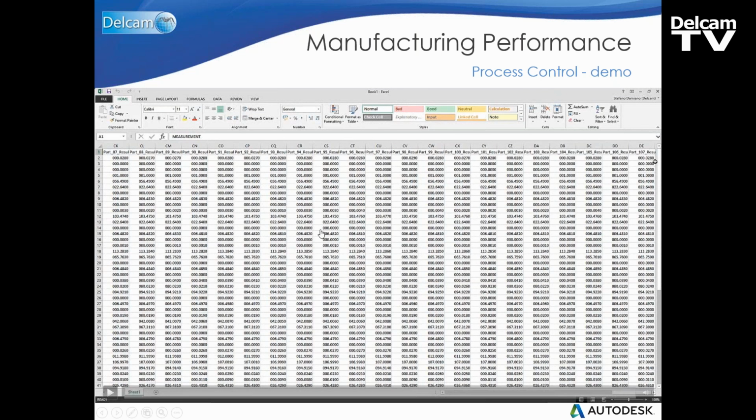We can use the data in the middle here to monitor how the process for a certain feature might fluctuate across the batch of components. And if we identify that it's getting close to our tolerance, or if we need to intervene, then of course we can update the coordinate system, or we can create a local part datum.